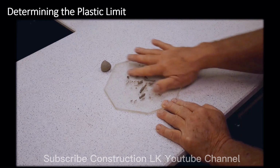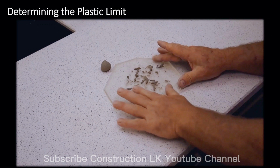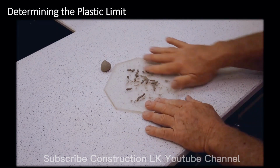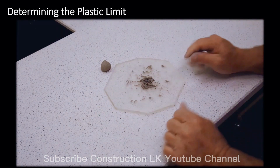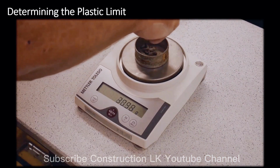This should be done over and over again, thereby reducing the moisture content till the thread crumbles when rolled to a diameter of 3.2 millimeters. Once the thread is getting crumbled at 3.2 millimeters diameter, the portions of the crumbled thread should be gathered and placed in a container to determine the moisture content.